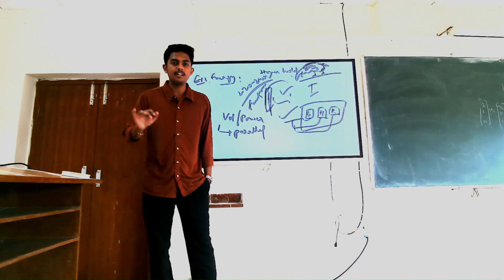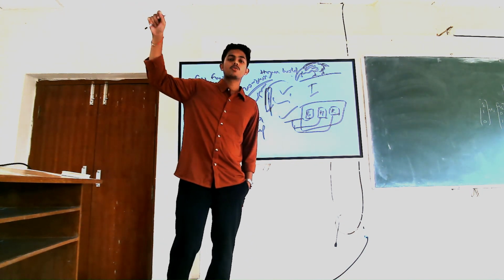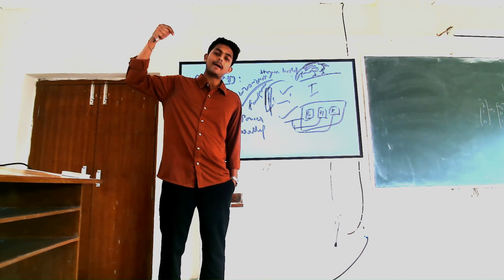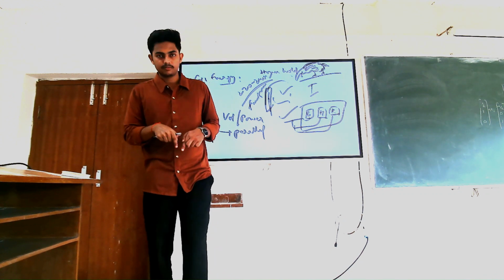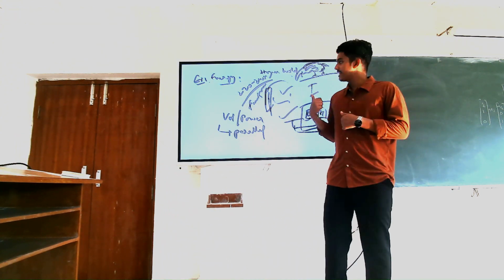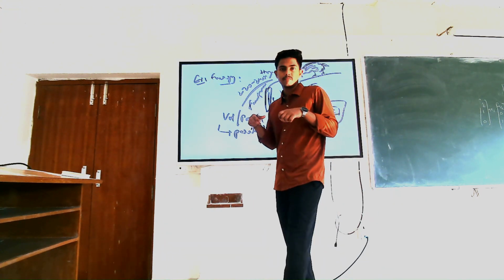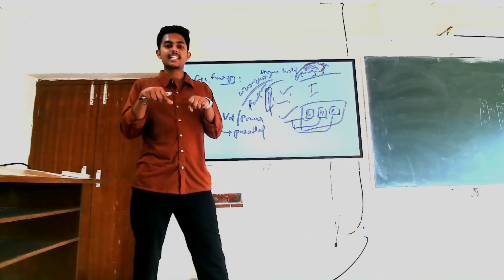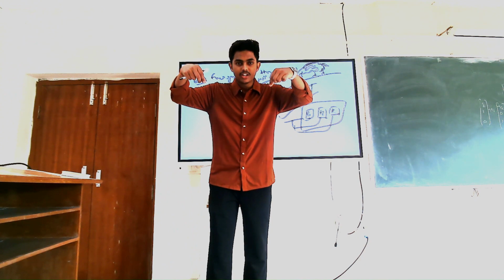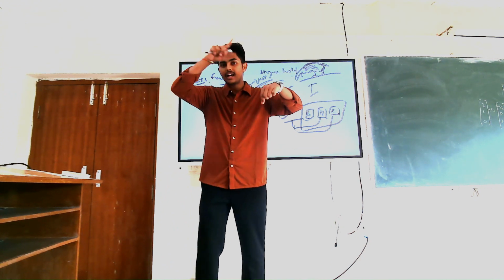If we catch a high voltage, electrons will flow from the high voltage to ground, passing through us, and we get shocked. But here, the two legs of the crow are catching the same wire. That means both legs are at the same potential. Between the same potential, the current won't flow.